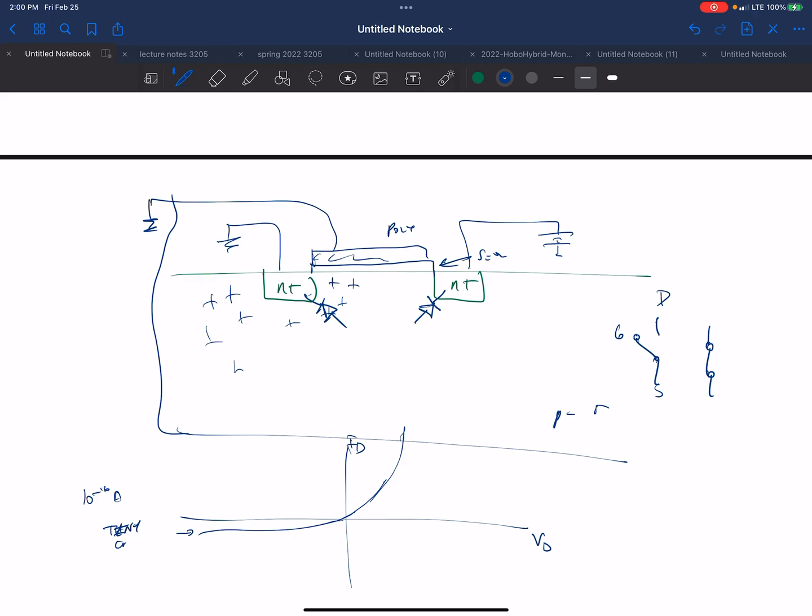It's called depletion, because you're depleting this area of holes. And then with even more positive voltage, you have your electron channel. It's called inversion, because you've gone from a hole situation to an electron situation. You've inverted your polarity. On this surface, you went from a positive polarity surface to a negative polarity surface. This is the verbiage people use.